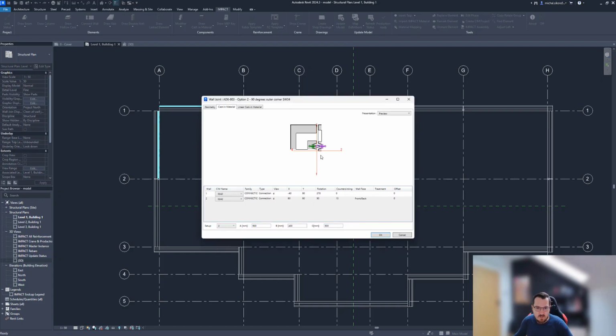And in this window, I can specify how many of those cast-in material wire loops I want. I can have a placement preview. Basically, that's the setup. That's the dimensions that I apply. So my A and B dimensions are by default 600 and 400 mil, and the spacing between the wire loops is 300 mil. And I'm fine with the settings as they are.